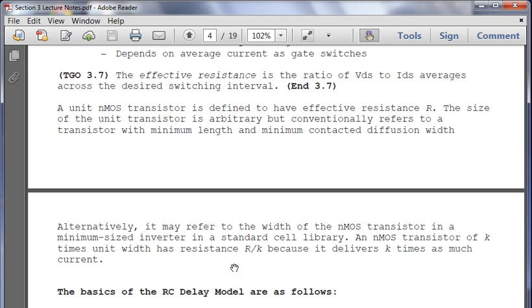So now we're going to go over the formal model where we're going to convert the PMOS and NMOS transistors into RC circuits. And based on that RC circuit, the amount of capacitance and the amount of resistance at the input and the output is going to directly correlate very closely. And we'll see the diagram, which is slightly different to the actual delay of the circuit.